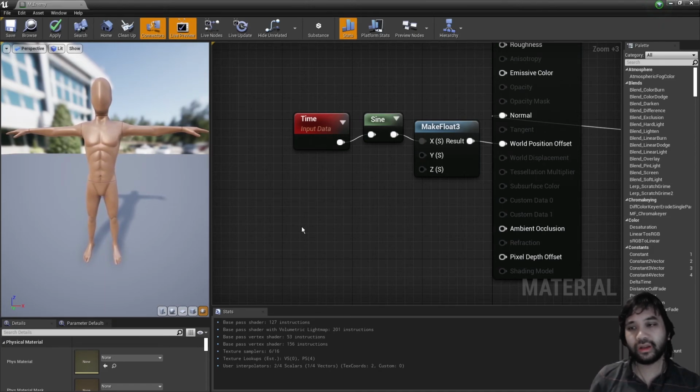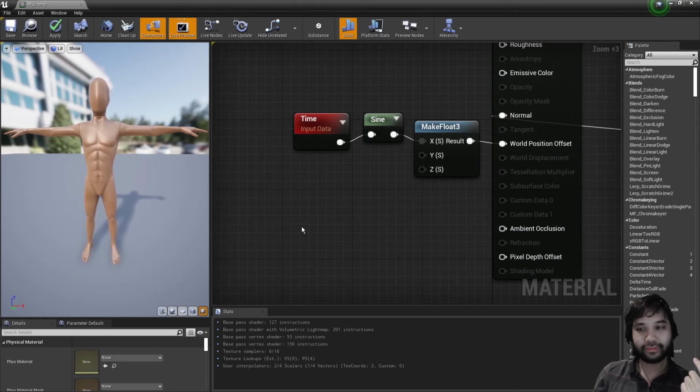So now can we improve this effect a little bit by, again, making it only sway at the top? Yes, by using a world position node. So before, we had to rely on the UV of the texture, because at the bottom the UV was 0, and at the top the UV was 1.